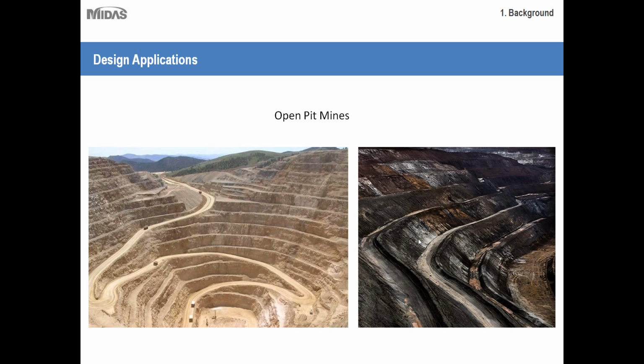Once again, if water is being stored in your slopes, that could cause a certain amount of weakness. So ideally what you'd want to do is drain your slopes before building them. That way they'll be very stable. So for those of you who are involved in mining, I'm sure this type of slope stability analysis is familiar to you.